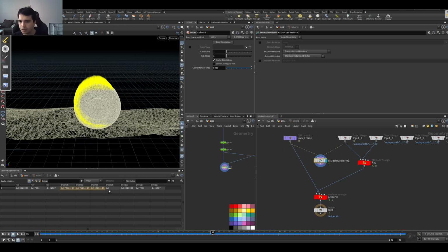You see there's an orient. So it looks throughout the geometry, so if I deform it here, it will mess it up. We will be doing the deformations outside. It looks throughout both geometries and creates a transform. It looks at the reference and target geometry difference and writes orientation differences as an attribute.